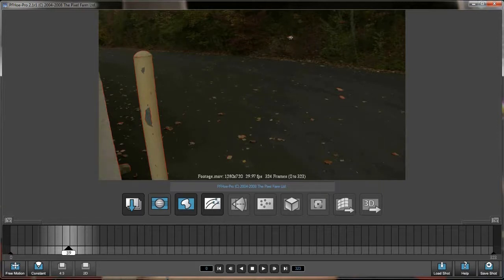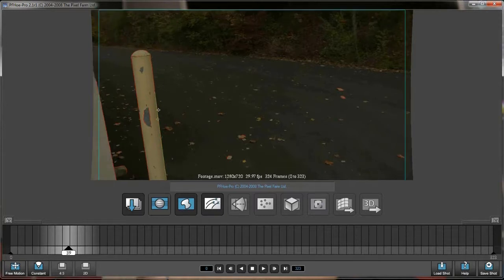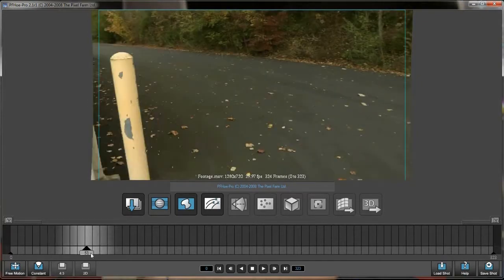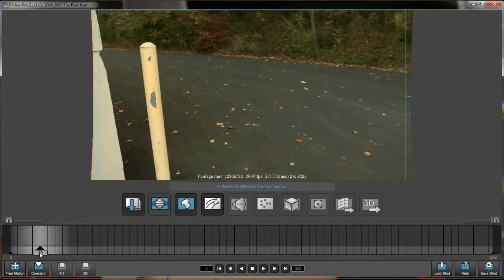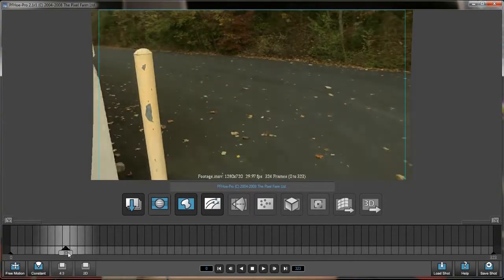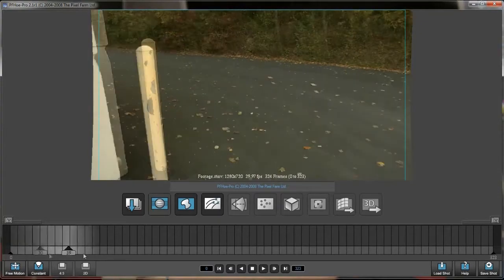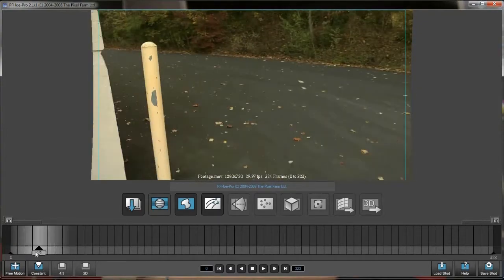Pretty much, there's a few up here, but basically wherever it sees a high contrast straight line, that's where it's going to point out. So here we got a really long one. It goes all the way here. So by just selecting that, what it does is it straightens that line and forces the whole footage, the whole composition rather, the footage out, so that it will compensate for the radial distortion. And so now as you play through, you can't really tell too much of a difference. It basically just eliminates that wide angle look, and it should make our tracking a little bit easier.